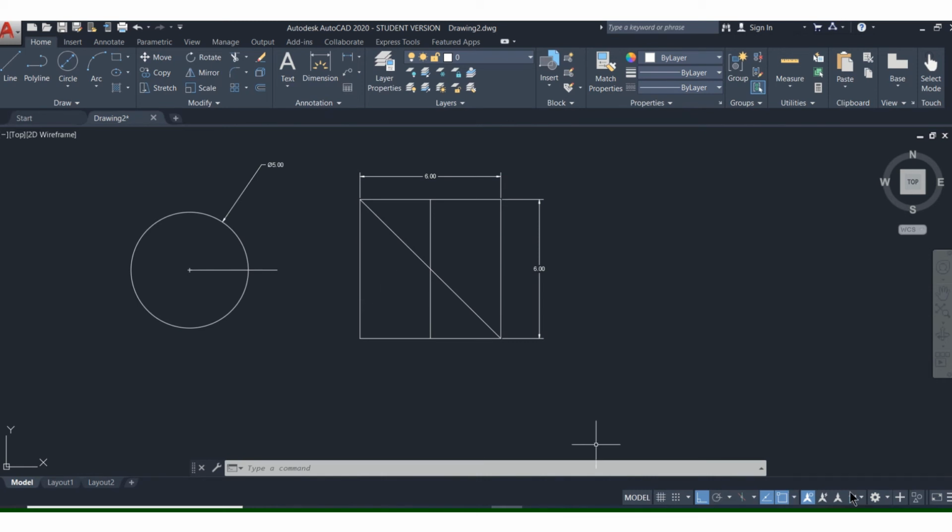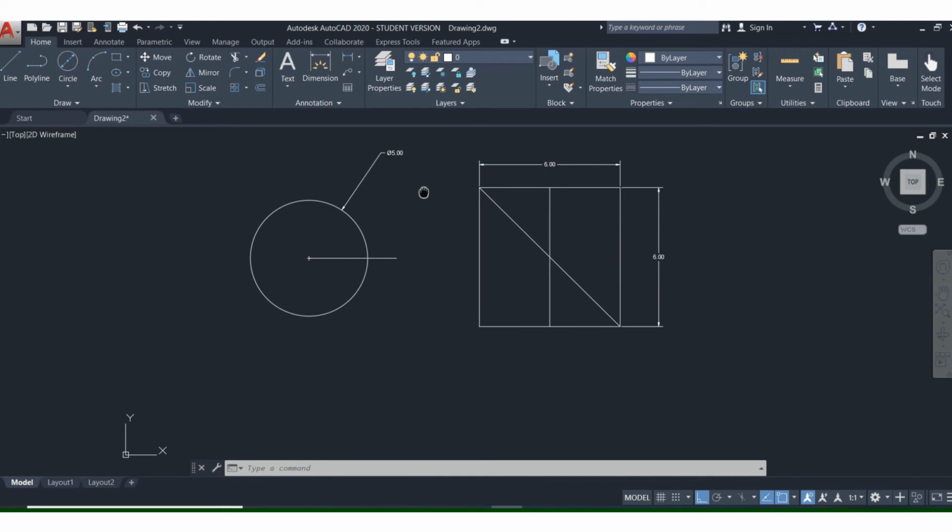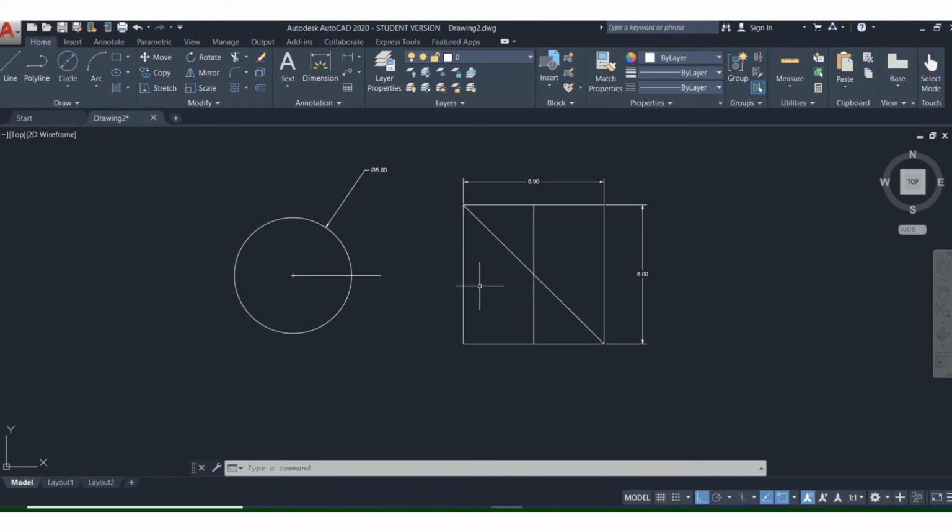Okay, so we've got these drawing tools set, you've got the number of decimals set for your dimension, and one last thing I want to show you in terms of setting, and that is the layout here. So you have 2 areas in AutoCAD. This is called the model space. So see this tab that says model, and this one that says model. You're in the model space now. The model space is the infinitely large drawing area that you have available to you.